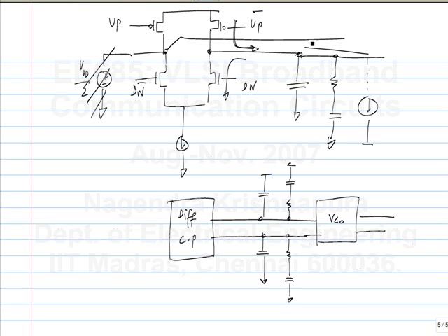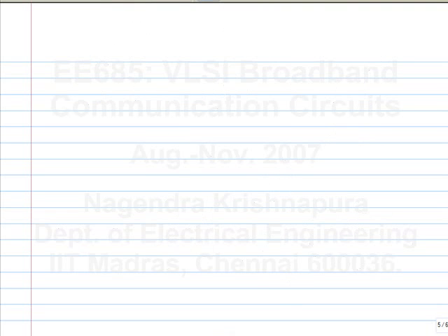Basically, exactly the same block will work with a data input if I find the right phase detector, right? The rest of the circuit is the same, at least you can intuitively feel that it is the same, because all that it is doing is, in response to a phase difference, correcting the VCO. So now I need a block that detects the phase difference between data, which doesn't have guaranteed edges every cycle, and clock which is periodic. What were you saying? You can have a counter after and depending upon how much output we get.